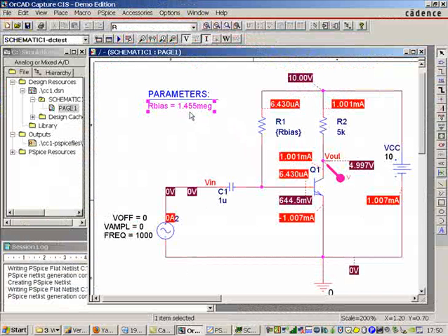You see I've already put that number in as a parameter, and this component has already been set up to operate with that value. So I've already calculated the bias. The bias should be 1 milliamp. We should be set at 5 volts. Everything's working very well. What I'm now going to do is delete these two components.